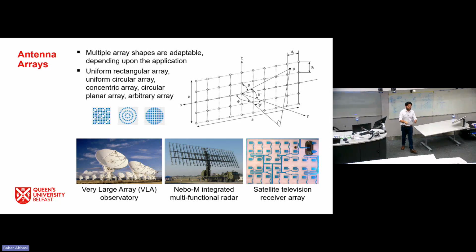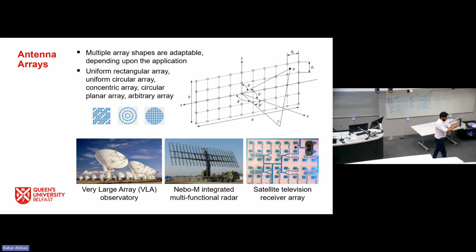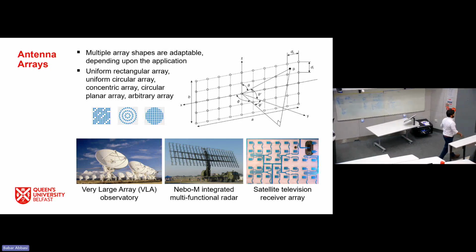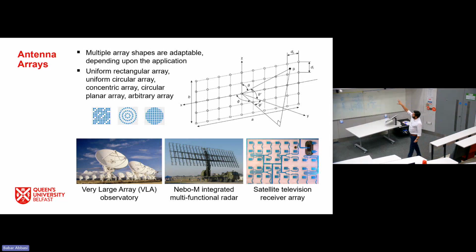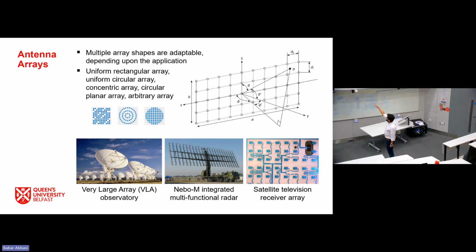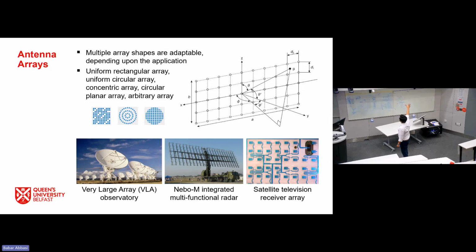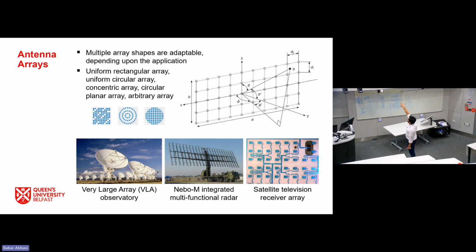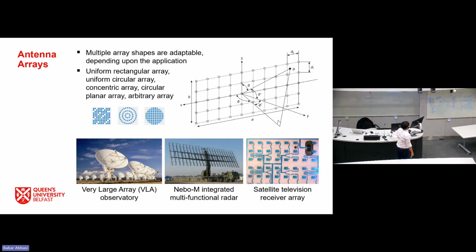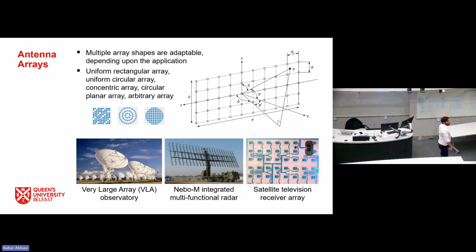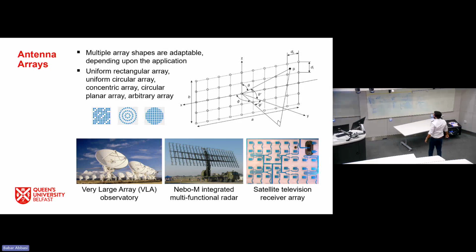and these transmission lines are basically metallic stripes with a given width, and each width of these transmission lines will define their own input impedance, and that's why it looks a little bit complicated. But if you just look at the theoretical concept, it's pretty reasonable. All antennas are, you can say, equidistant on the top side and equidistant on the bottom side, so they can be considered as a 3 cross n rectangular array and an array of arrays. So they're kind of an array of arrays.